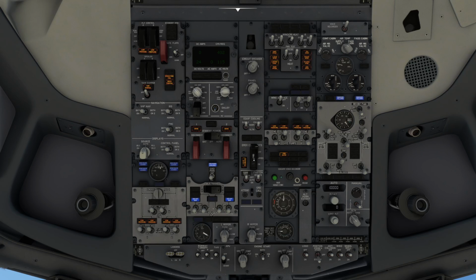First thing we do once we have power to the aeroplane is turn the emergency lights to armed and close the switch. We also confirm that the position lights are on steady, which they should be out of the box with the aircraft. I think the reason it's left on steady is that as soon as the aircraft has power, the lights come on at the end of the wings to tell anybody around the aircraft that there's somebody inside getting it ready. So not under the wings, underneath the body.